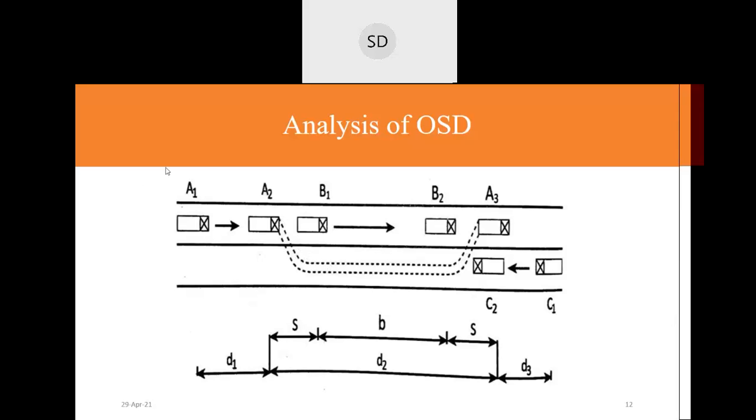And this time from A1 to A2 is the time in which it is assumed that he overtakes, within his reaction time t second. So this distance, that is the d1 distance from A1 to A2, would be VB into t, or 2 into VB, because here the reaction time is 2 seconds.